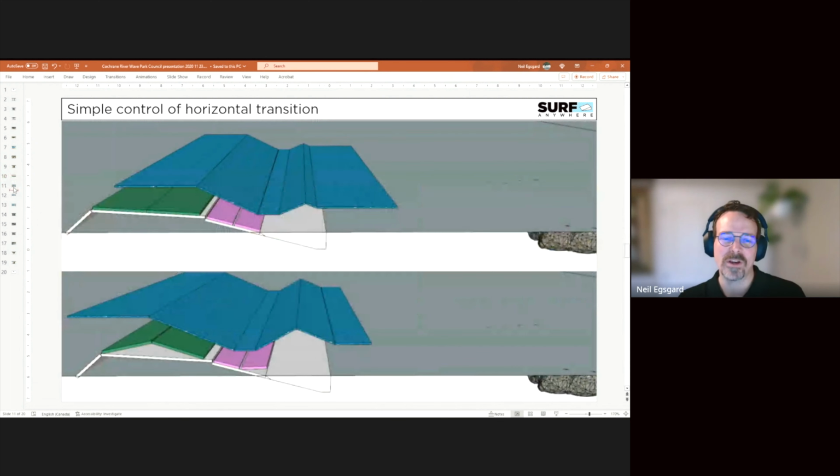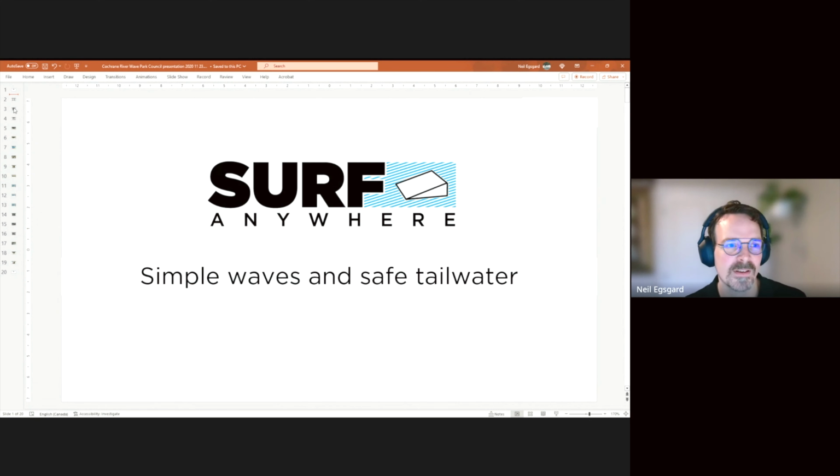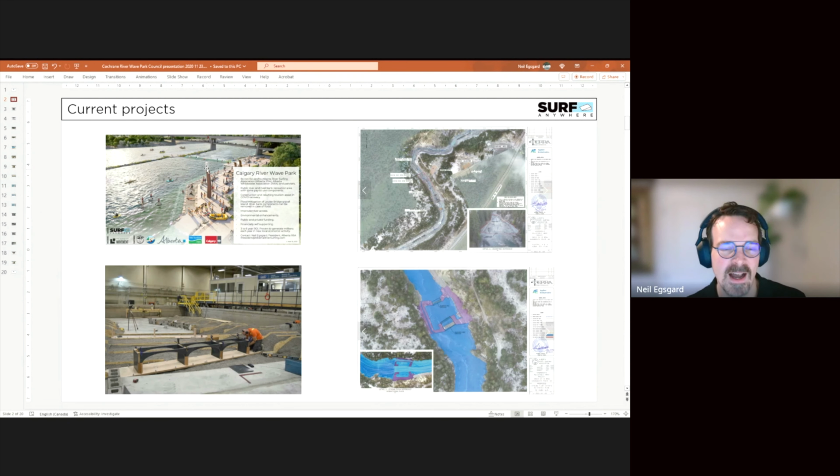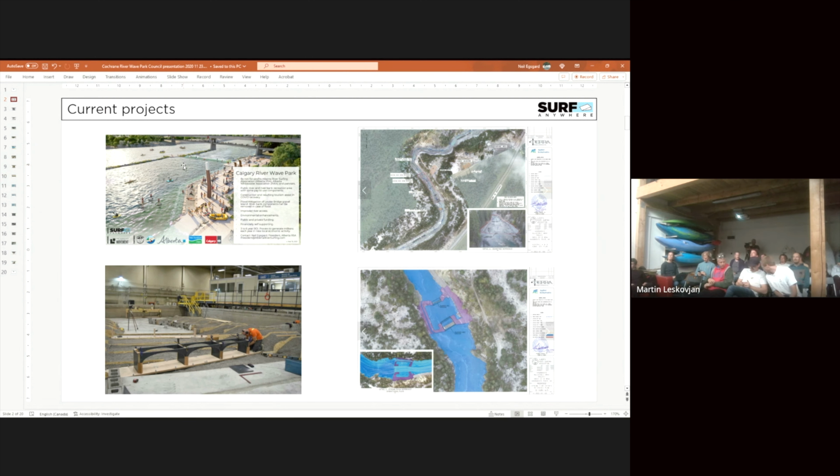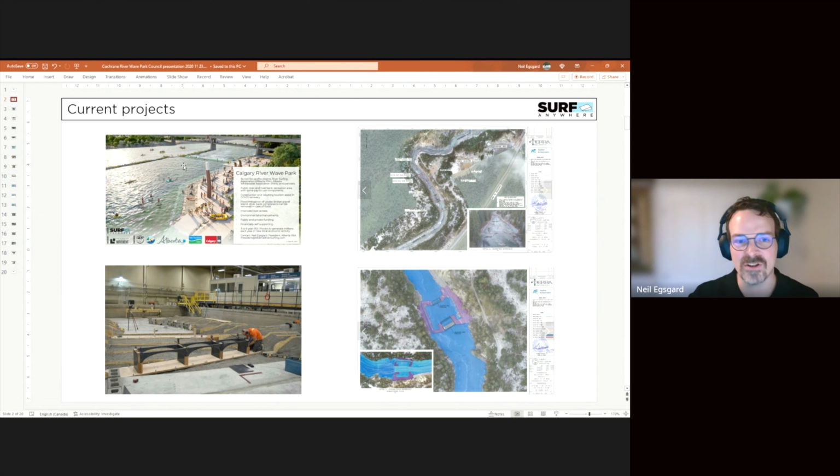So this is the concept that we're working on. We're doing the preliminary engineering on it in our large wave project. This one here. We have tailwaters that increase from low flow conditions to high flow conditions by about 1.5 meters, I think it is. The flows go from 50 CMS to 300 CMS, the stage where we have to lower the structure, and then the 1 in 100 year flood is 2,000 CMS. So during that operational range of 50 to 300, we have a tailwater change of about 1.5 meters to 2 meters. Maybe that's a bit high. Let's say 1.5 meters.